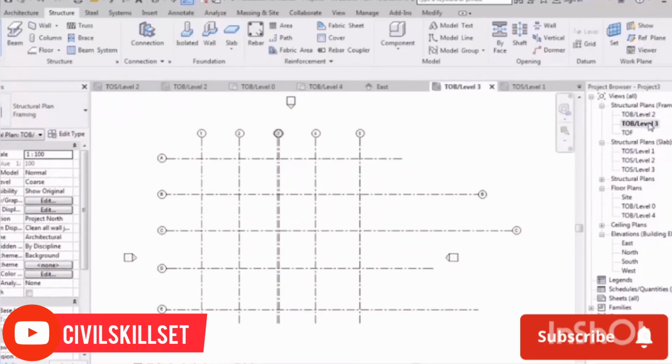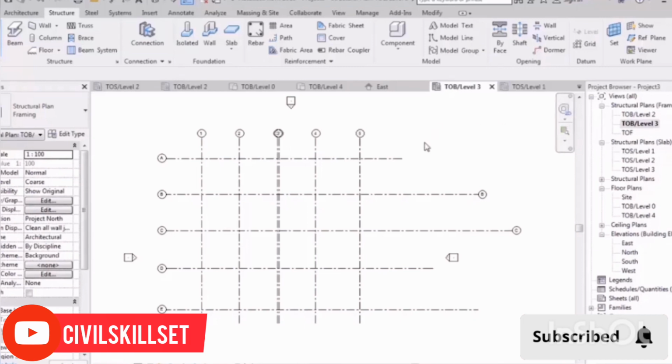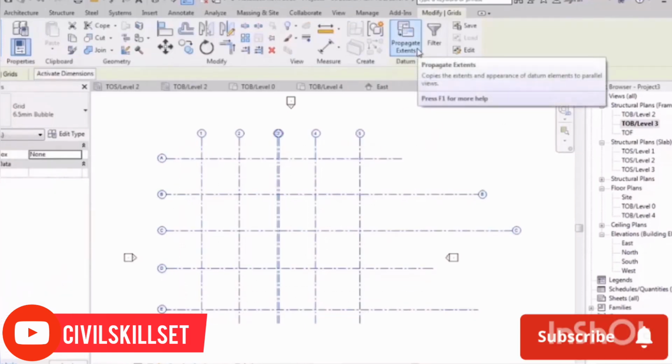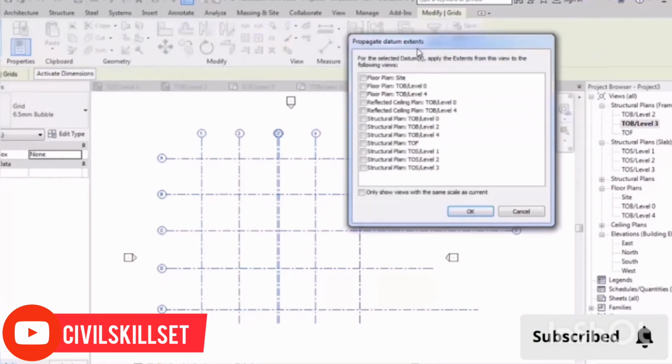So there's a technique that we can move the graphical settings of the grids from one level to another. How? Well, select it first, then click Propagate Extents. Now it asks us which of these levels we want it to be moved to.